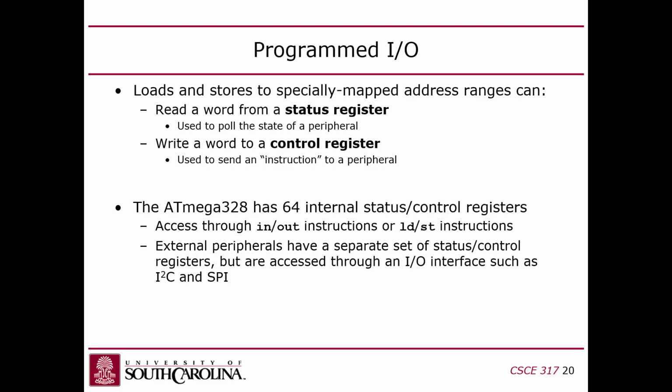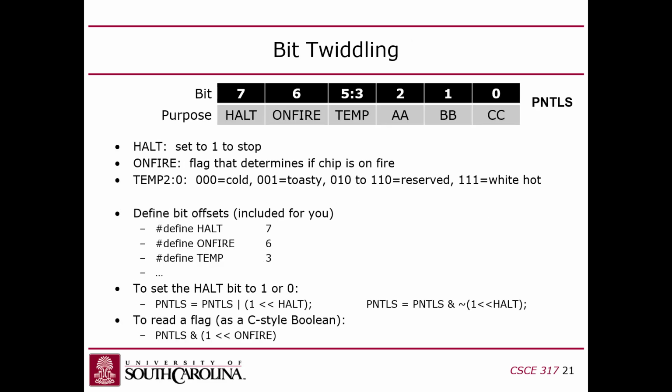So there's 64 registers specifically in this chip that are used as status/control registers. I think they call them I/O registers, right? But basically, there's 64 8-bit locations that are used to control and monitor hardware. So how do we do this bit twiddling in software?